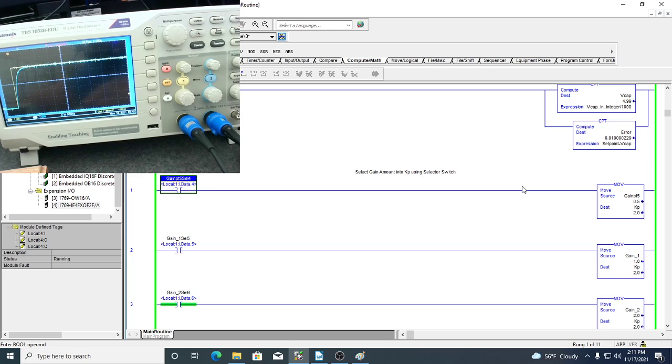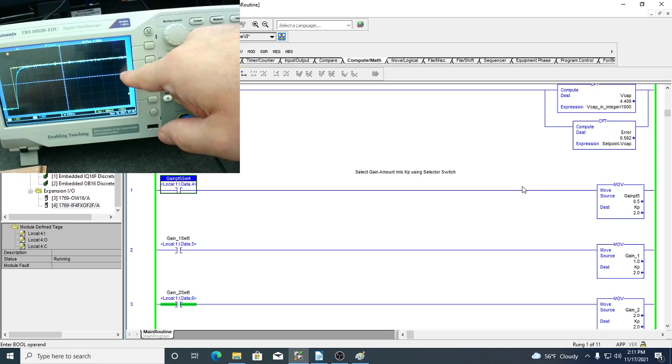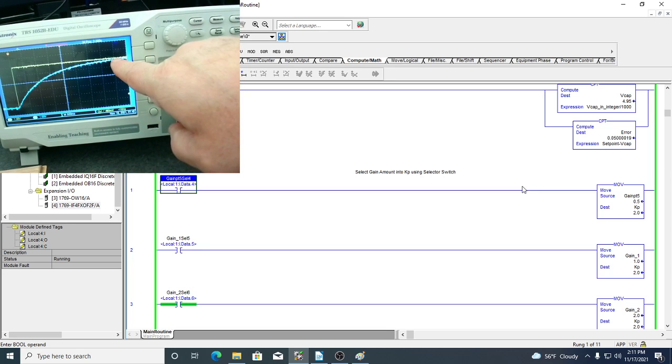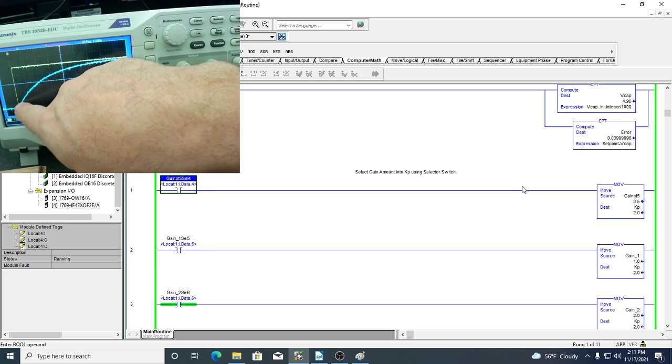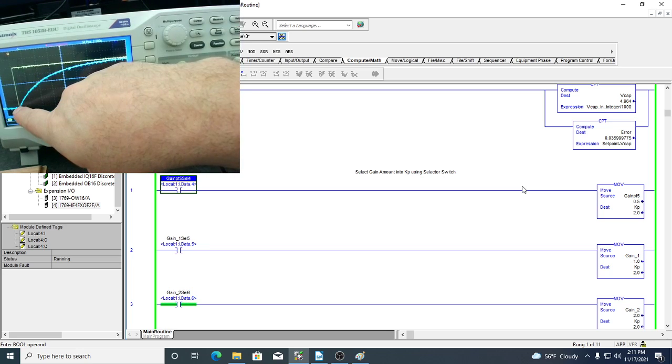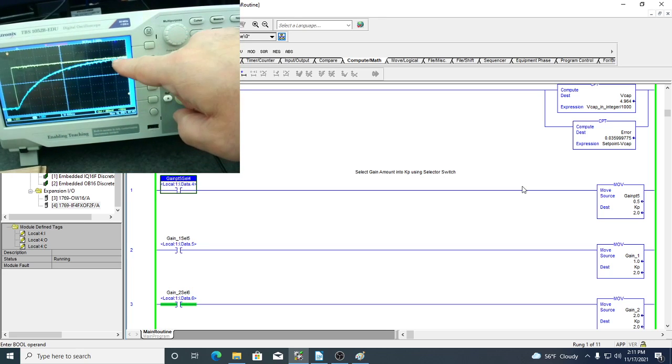I'm now going to flip the switch into the 1K, and I'm going to run it again, but I'm using a 1K ohm resistor instead of a 50 ohm resistor. And so I trigger it, and it's collecting the data now, and what you're going to see is how long it's taking to charge. That's because it's 1,000 ohm compared to 50 ohm, so it's taking a long time for that capacitor to charge up. Okay, that is open loop. Both of these are open loop with the 2 different resistors.